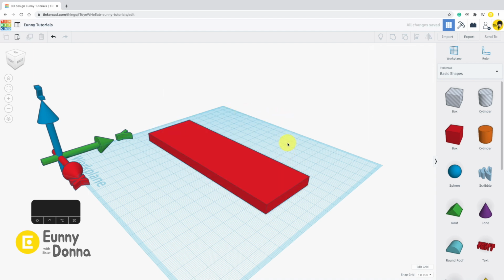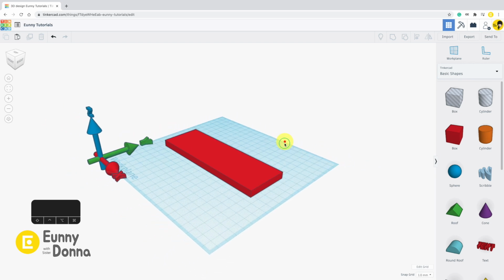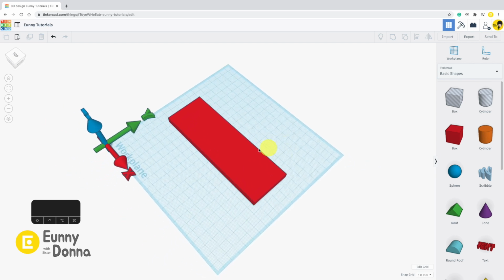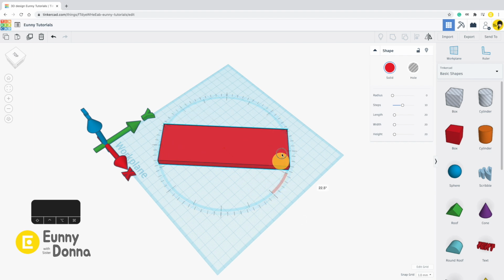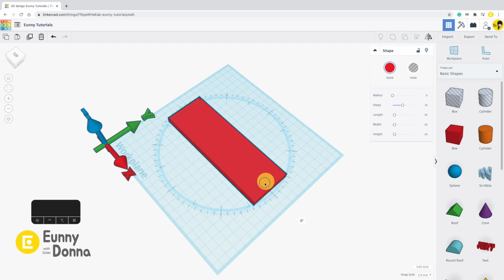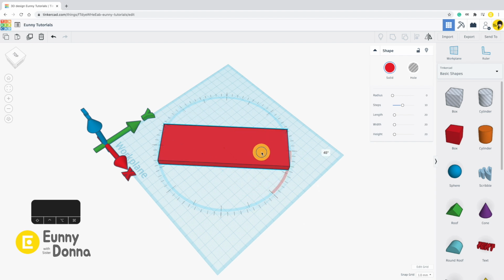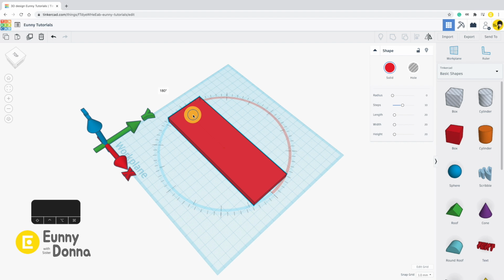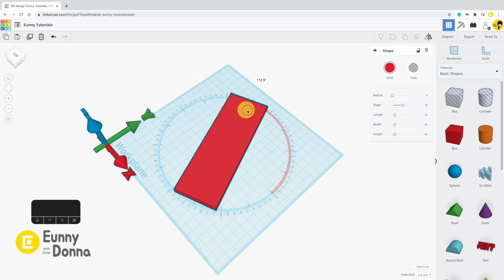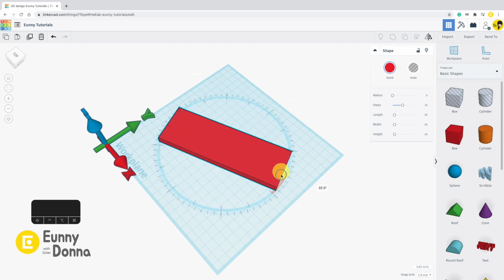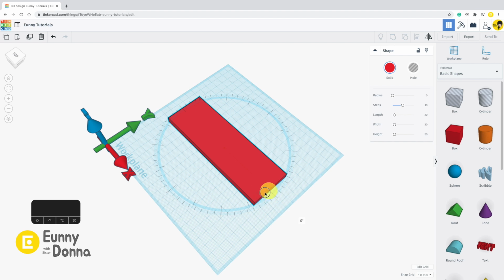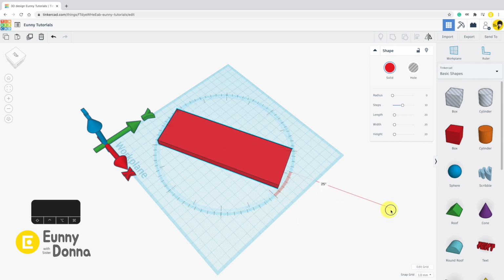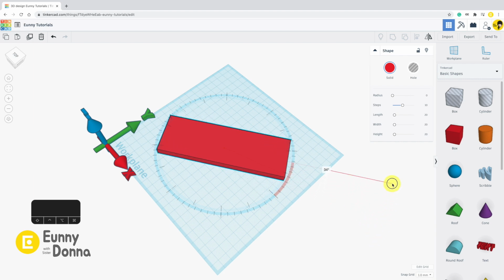There is one hidden tip in this function. When you click arc points and get your mouse closer to the shape, you can use snap degree. Snap, snap, snap. You can see the snap works by 22.5 degrees, 1/4 of a right angle. This function makes it easier to rotate shapes in 90 degree and 180 degree sharply. If you get your mouse far from the shape, of course you can rotate it by 1 degree delicately.